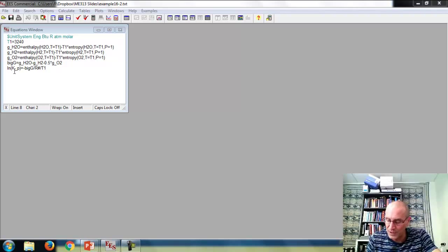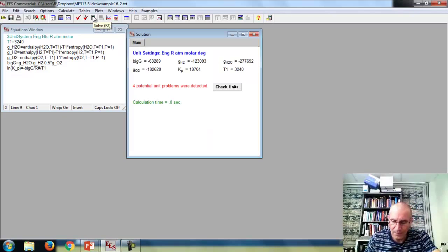And now I'm going to find big G, that's my big G star, and it's just equal to G of water minus G of H2 minus 1/2 G of O2. There are stoichiometric coefficients of 1 for the water and the H2. And then I can say, find the natural log of Kp is minus big G over RT. So it's pretty straightforward. If we go ahead and solve this now, here I go, and I find my big G at minus 63,000, and Kp is 18,700. Okay, that still seems like a big number, but it's nothing like 10 to the 40th.